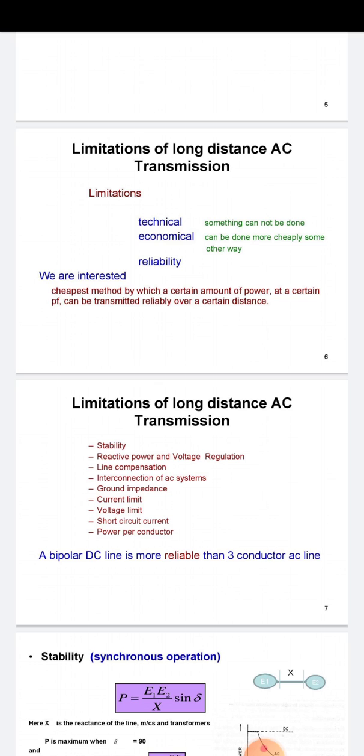The characteristics of insulators vary with the type of voltage applied. For simplicity, if it is assumed that the insulator characteristics are similar for AC and DC and depend on the peak level of voltage applied with respect to ground, then it can be shown that for lines designed with the same insulation level, a DC line can carry as much power as an AC line.